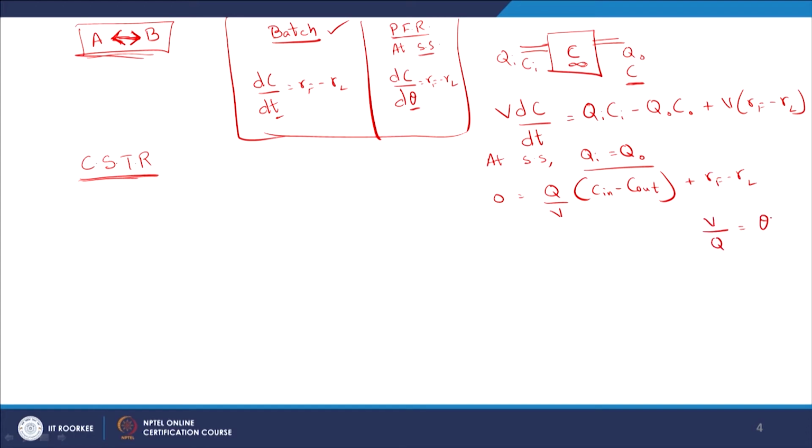That's theta, or the hydraulic retention time. HRT gives you an idea about the average time a water molecule spends in your reactor. That average time is given by HRT, hydraulic retention time. So V by Q is theta here. Where are we here again? I'm going to bring this particular term out to the left hand side.